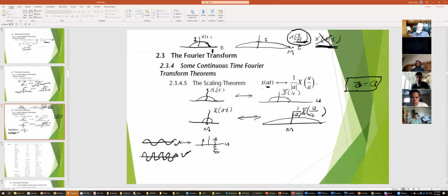So what do we have to do over here? We have to make this bigger, don't we? The frequencies have to be way out here, by whatever factor we squeezed the sinusoid in. So these frequencies have to be much higher. We see an intuitive manifestation of the scaling theorem here. If we have a sinusoid with certain frequencies, and another higher frequency sinusoid, this higher frequency sinusoid can be thought of as that slow sinusoid pushed together, scaled together.